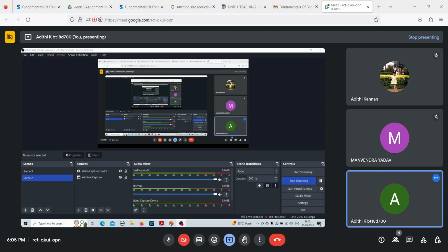This is known as the work index. And since work index is the energy required, the unit is kilowatt hour per ton. The work index of a particular material can be determined in the laboratory by conducting something known as a Bond grindability test. The answer here is option B. That is from infinite size to 100 microns, where 80% of the particles have this size. We will be solving some numericals regarding this work index as well. Hope this is clear. Any doubt on this?